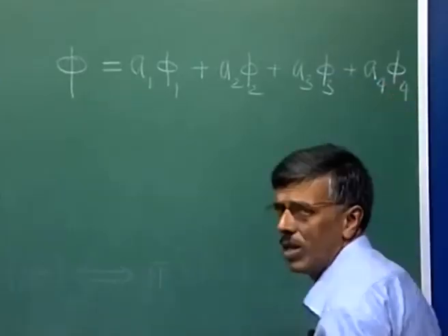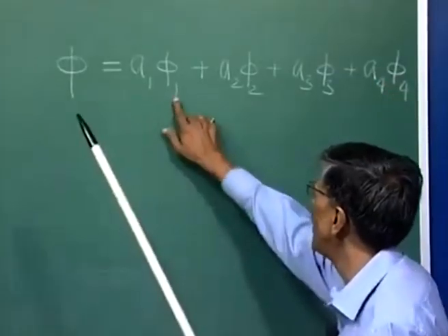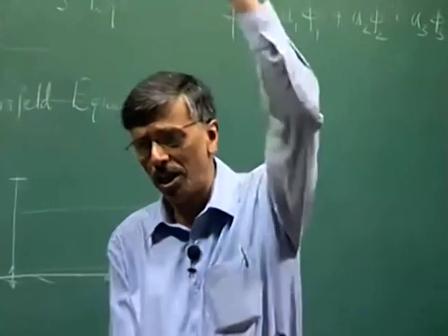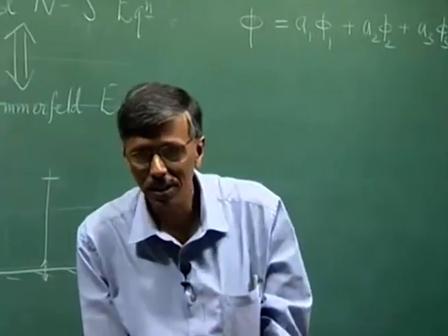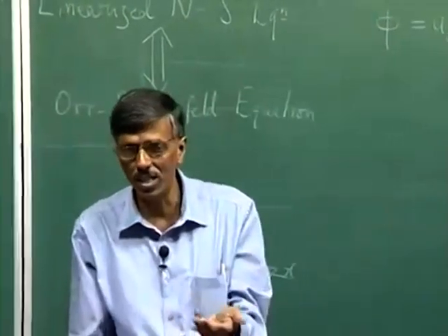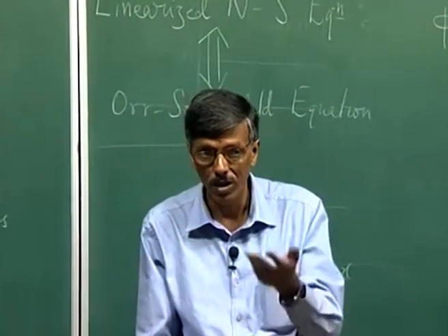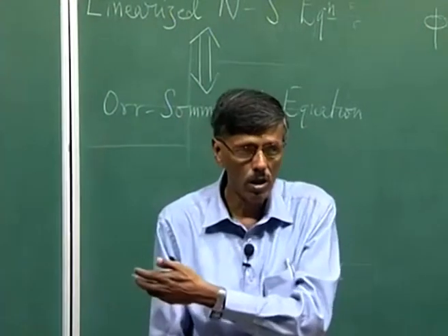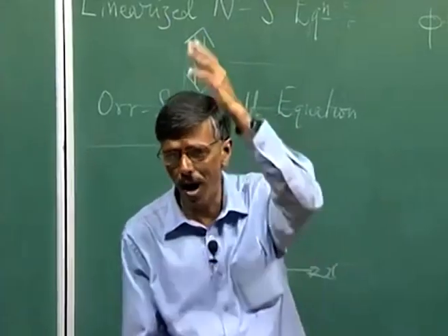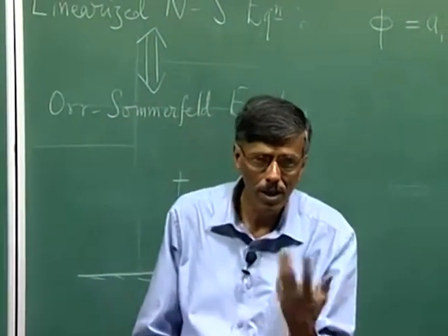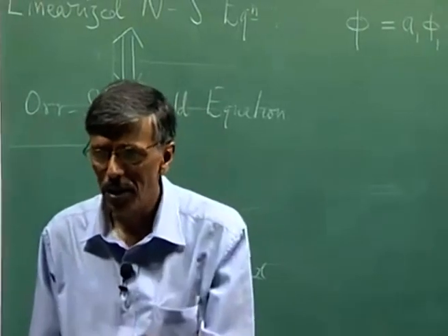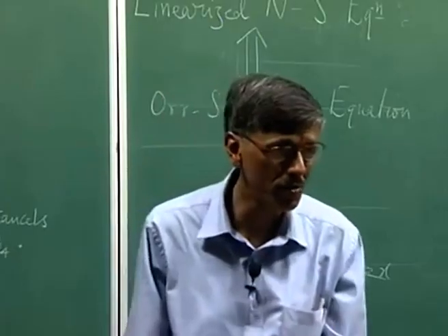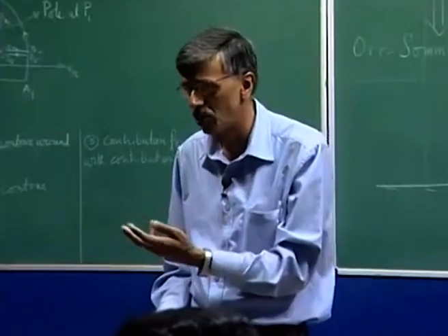What do we know about these individual modes phi 1 to phi 4? Well, we only know them when we go outside the shear layer. Recall, that is how, in defining the initial condition for the compound matrix method, we evaluated those modes. You can substitute your condition of y going to infinity. What will happen? U of y will become 1, U double prime will become 0, and then we will have a constant coefficient 4th order ODE, and we get those 4 modes.